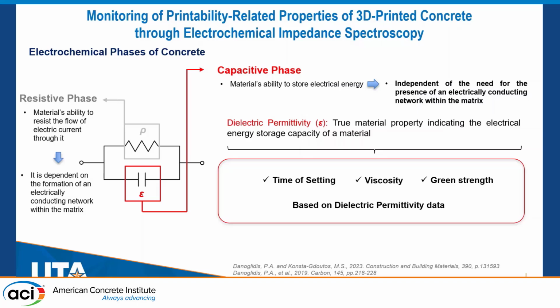So in this study, we used dielectric permittivity data and correlated dielectric permittivity data with the time of setting, viscosity, and green strength. And I will walk you through this in my presentation to see if we can use, finally, electrochemical impedance spectroscopy to predict, to simulate the properties.